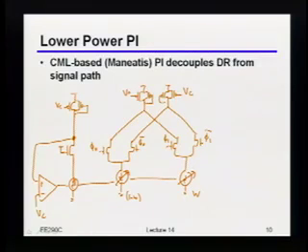Because this is not the same as the PLL anymore. In the PLL, I really wanted those inverters, okay? Now, you could build your PLL so that it looks like this, but this tends to have more headroom issues. It tends to not give you as good of a phase noise for the same supply voltage. There are some other, more detailed things, but indeed, you tend to want to use the inverters inside of the PLL and this inside of the phase interpolator. So that kind of sucks, right? Because now they're not the same.